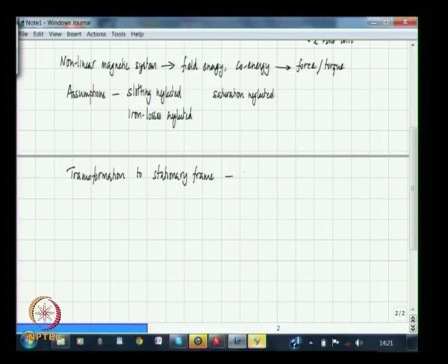And we found that indeed in this reference frame the inductance matrix is constant, there is no dependency on the rotor angle. But having reached this point, we found that this representation, where you have 2 coils on the stator and the rotor coils which were rotating now transformed into the stator reference frame, the resulting set of equations could be used to model a variety of machines.